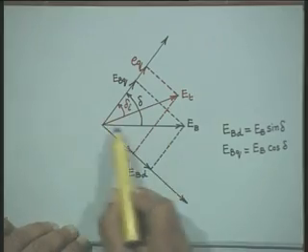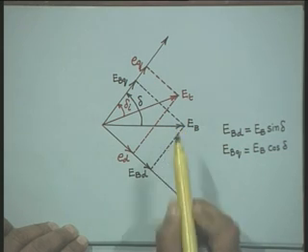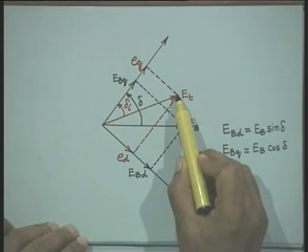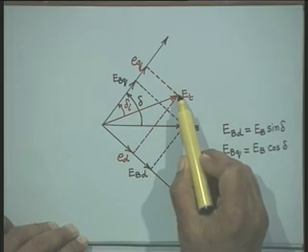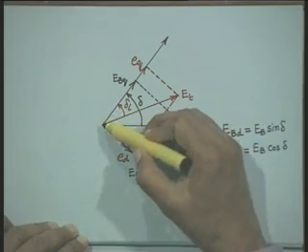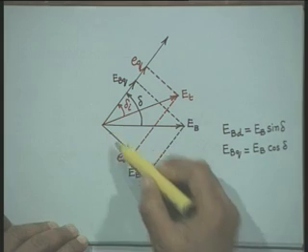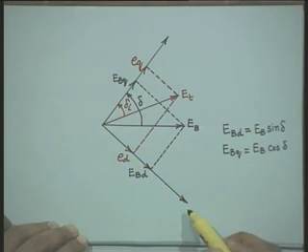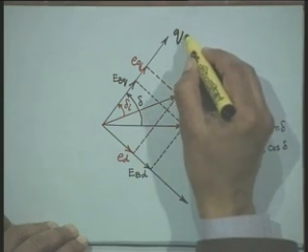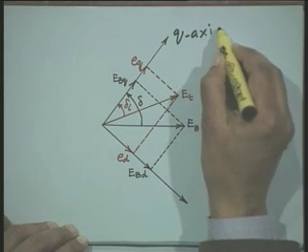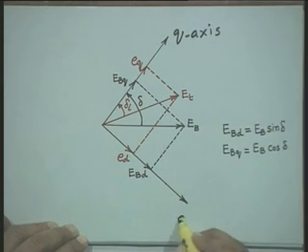The position of the rotor with respect to the infinite bus voltage phasor can be expressed in terms of q axis. That is, here if I represent this as my infinite bus voltage, and this is the terminal voltage of the synchronous machine, if this is my q axis, this is E D, that is the d axis, and this is your q axis. This is all known to you, and this is your d axis.